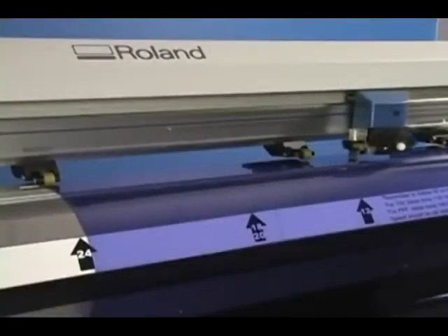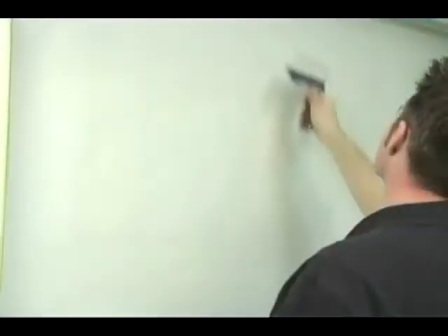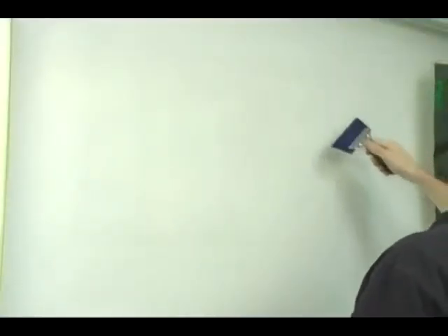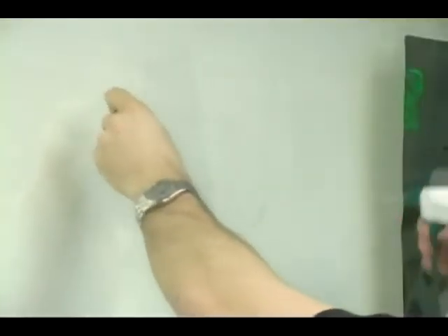Once all of your cuts have been made, it is time to prep the graphic for installation. It is important to keep your work areas and your film clean and free of dust or debris. A good tint install must not have any dirt between the film and the glass. Start by applying your transfer sheet to the glass with the liner facing out. Remove the liner while spraying the exposed adhesive.